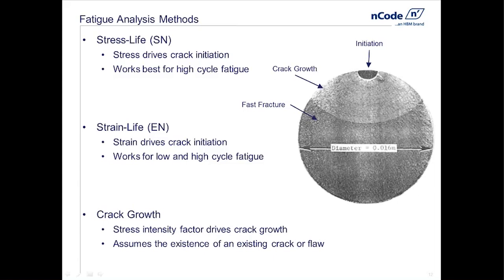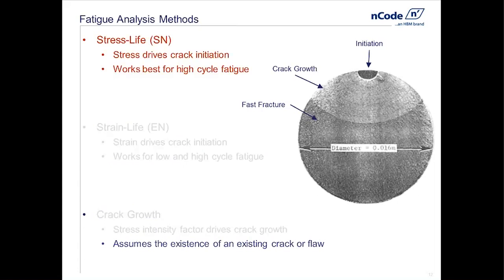That uses this thing called the stress intensity factor. Rather than looking at stresses or strains, we're going to look at this new parameter called stress intensity factor, which comes from linear elastic fracture mechanics theory, and we'll dive into that in just a little bit. We're going to start, though, by looking at the stress-life fatigue method. So stresses driving fatigue, and it works best for high cycle fatigue.